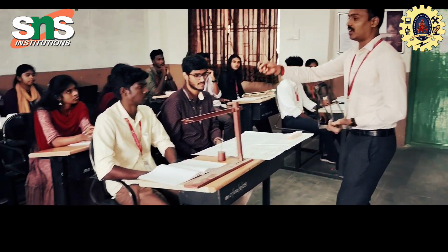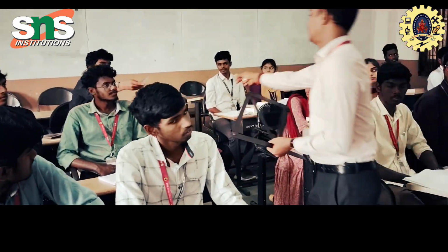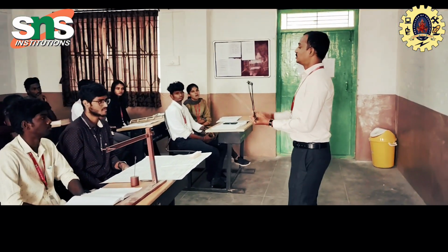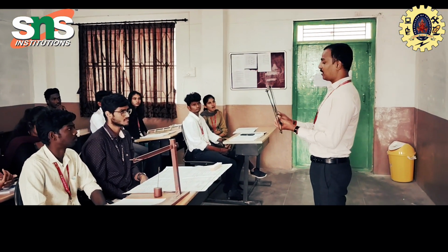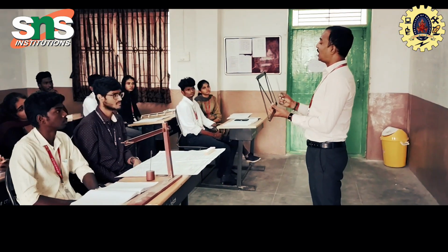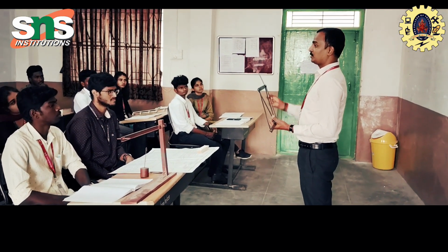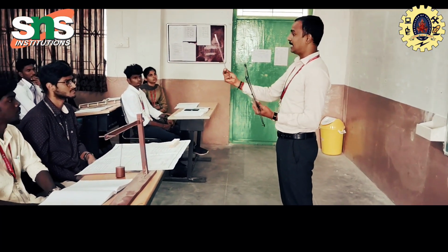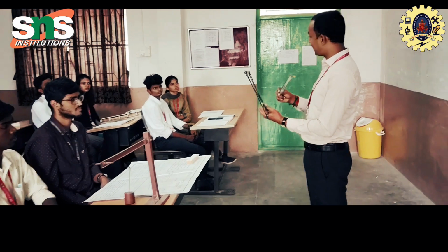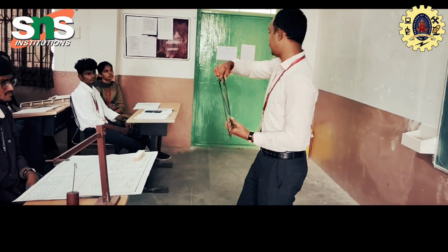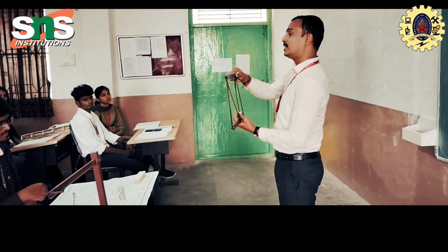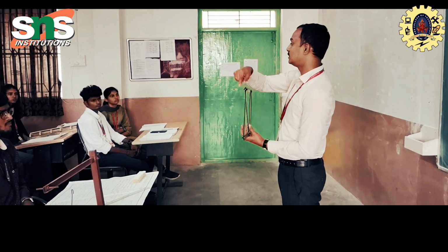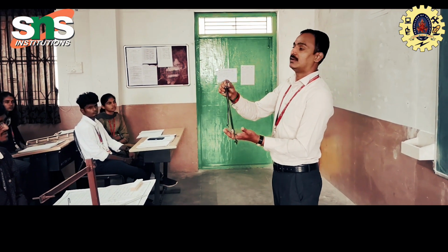So it is a combination of bar elements. We have 2D truss and 3D truss elements. Once you see the bar element, n number of bar elements are joined by pin joints. We know the bar element takes only compression and tension load. Similarly, these n number of bar elements are placed at different angles and joined as pin joints. The pin joint is the important thing in the frame where the load acts. That's why we call this a truss element.